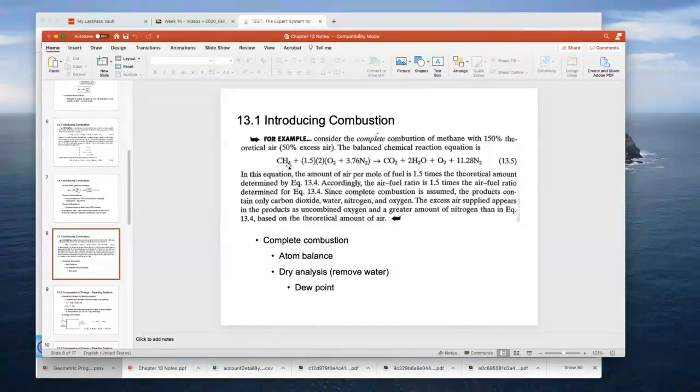What we'll do is specify the temperature of mixture A, the temperature and pressure of mixture B, and then we'll set the pressure of mixture C to be 1 atmosphere, and we'll allow the first law to calculate what the temperature must be if there is no heat transfer.